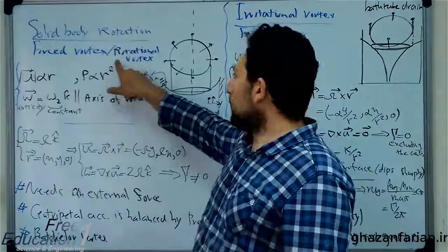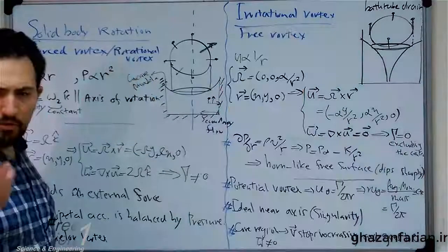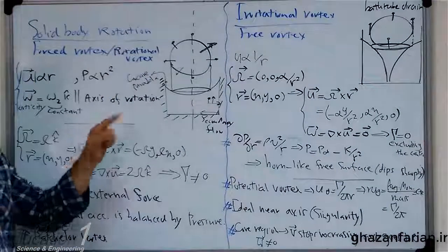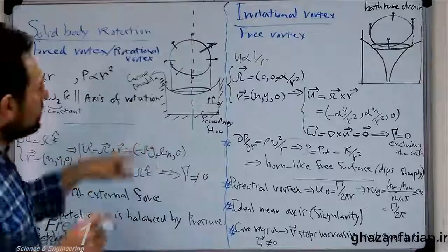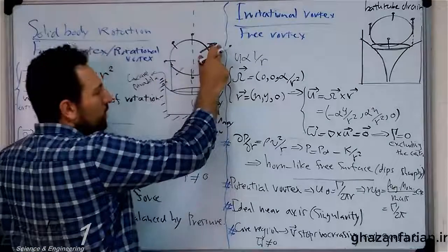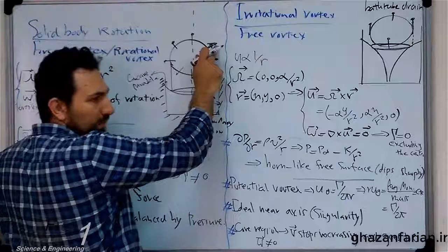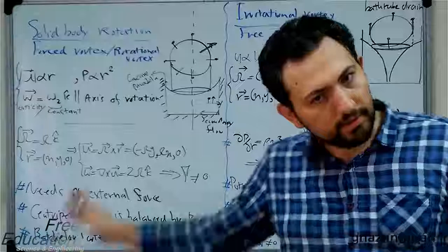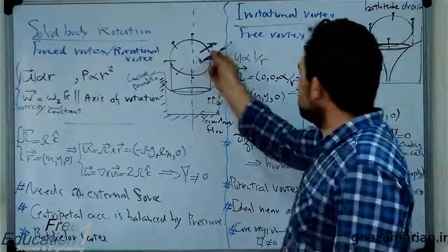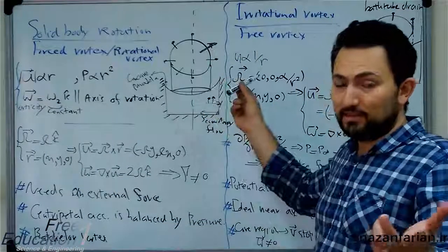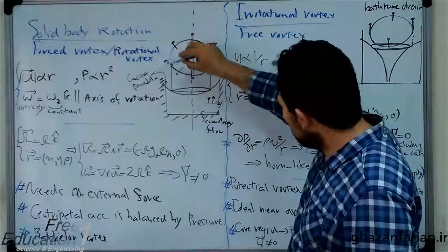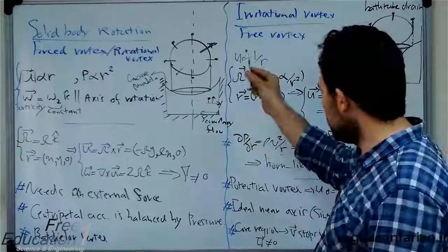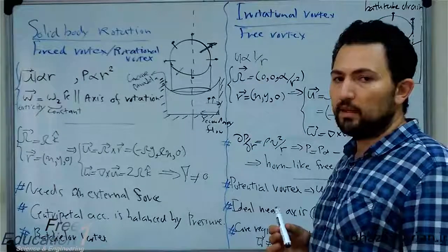As you see, the vortex is rotational. In order to visualize the motion of the fluid and the rotationality of the flow field in the forced vortex, put a piece of wood with a sign on one end on the free surface of the rotating water. In this case, you will see that the motion of this visualizer, let's call it the visualizer, is something like this. This shows that the axis of this visualizer rotates,